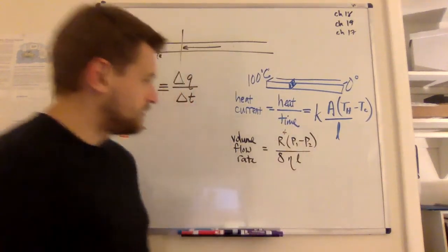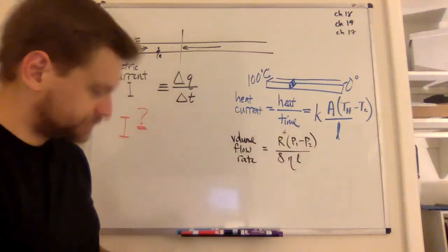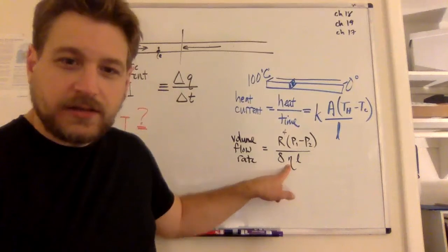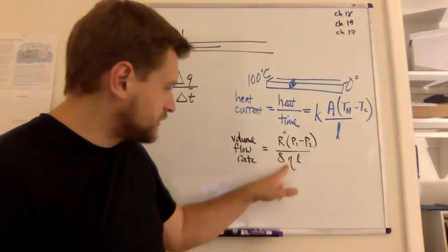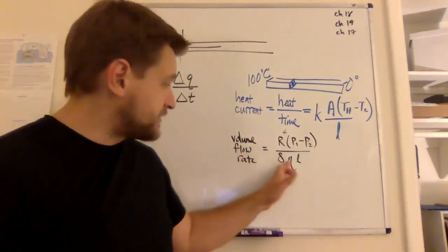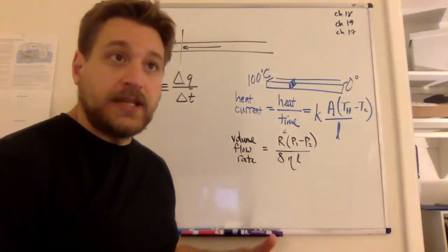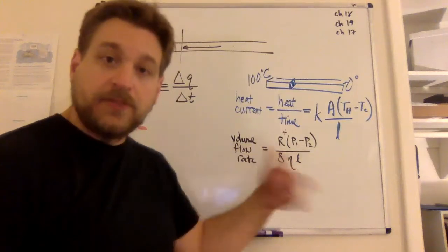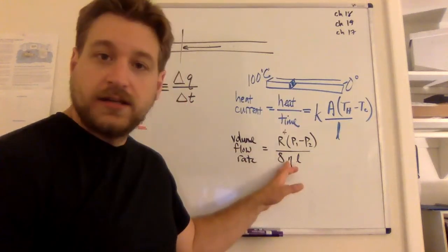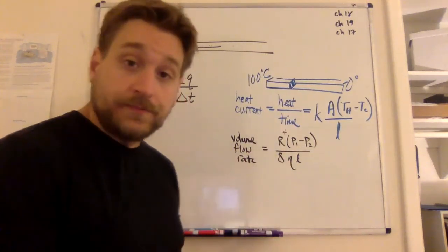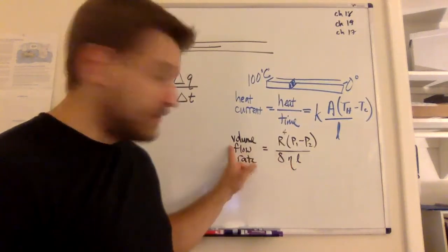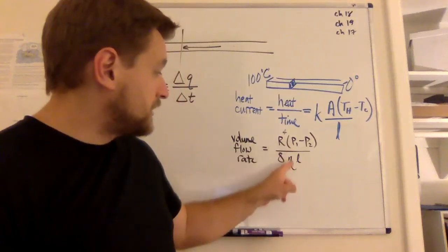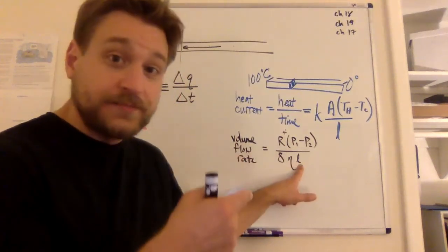Divided by 8, something like that. This N with a kind of a trunk is eta, and it's the viscosity of the fluid. It's in the denominator because the more viscous the thing is, the more it resists its own flow. So the greater that is, the less the volume flow rate, because the fluid is resisting its own flow. The length is still here.